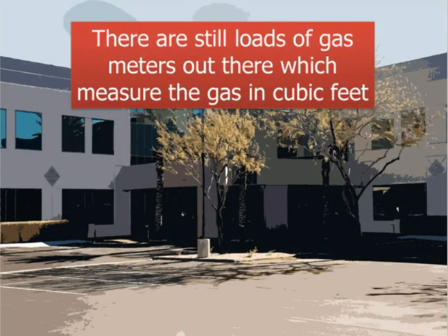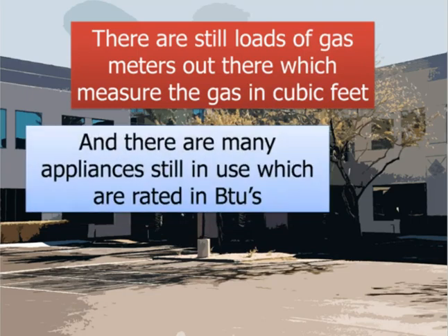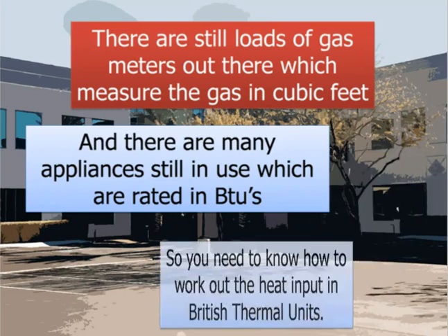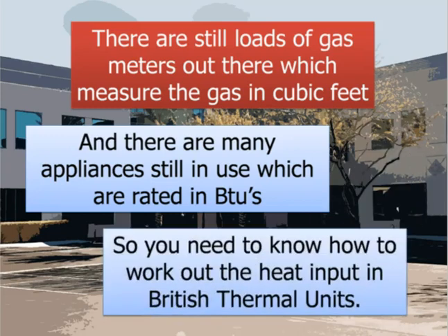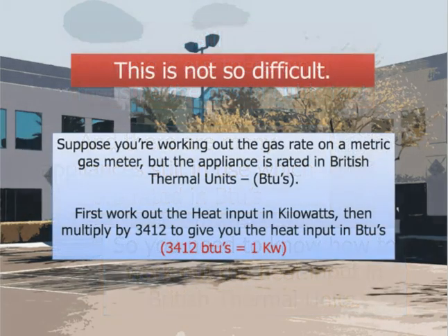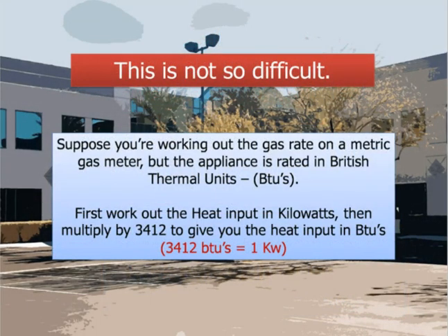There are still a lot of gas meters out there which measure the gas in cubic feet. And there are many appliances still in use which are rated in BTUs. So you need to know how to work out the heat input in British thermal units. This is not so difficult.